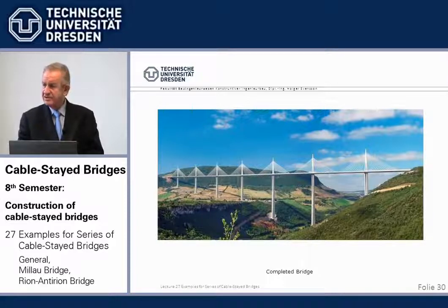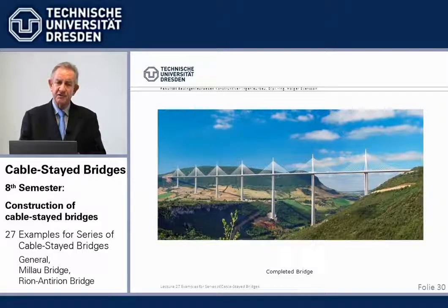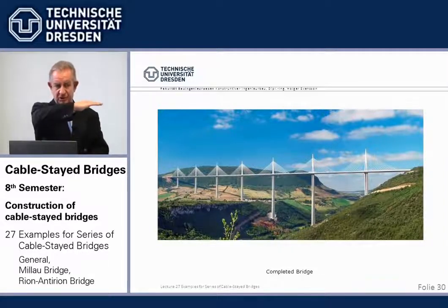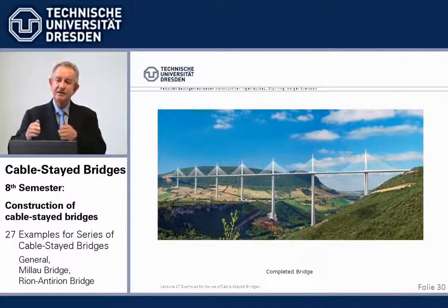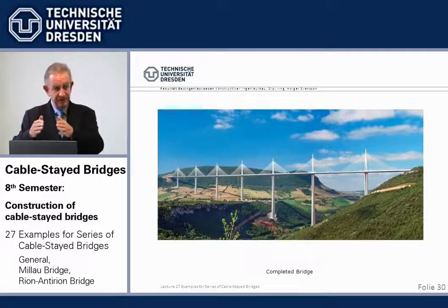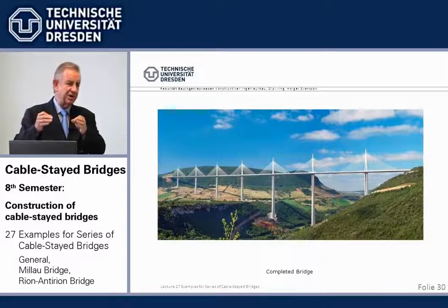And construction, the launching itself on 342-meter end spans is something. Then we launch 4 meters too high to save the money and bend it down. And we have the final towers modified as auxiliary supports at the tip. Those are quite a number of outstanding ideas coming together in one bridge.